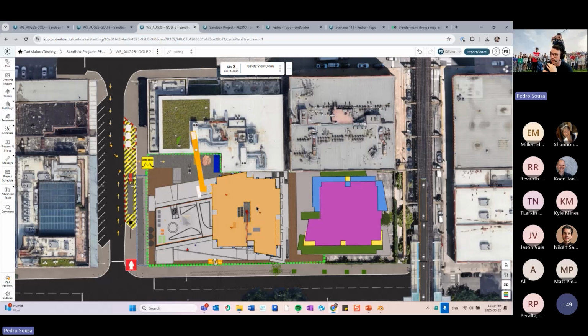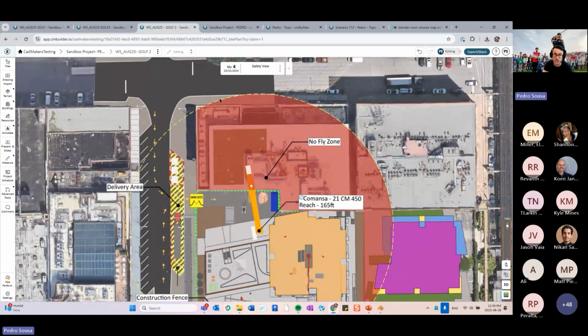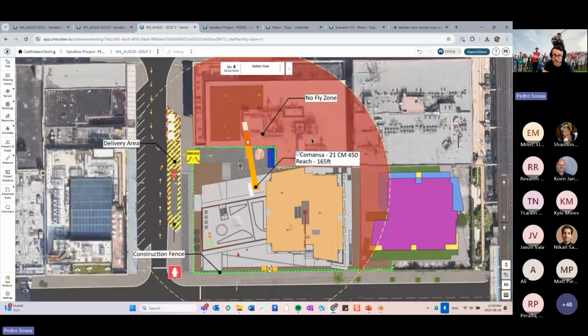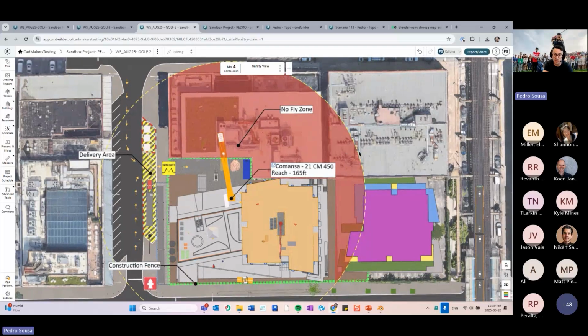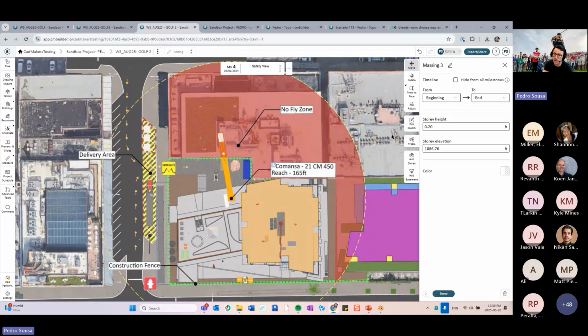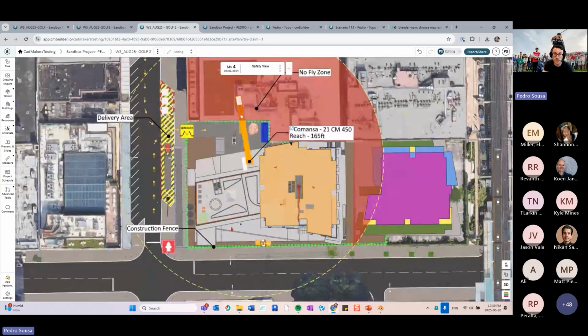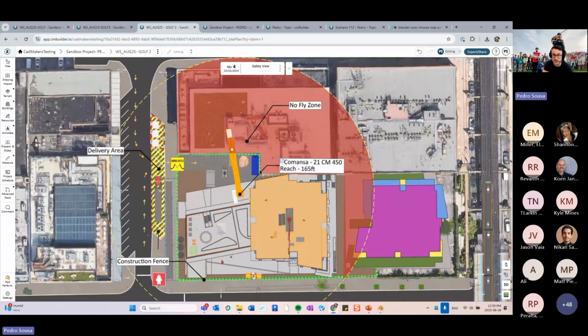Another point that I really stress is to really use the annotations. So callouts, lines, and zones, like I did over here, right? So I created a line to represent the crane radius. I put a lot of callouts to highlight elements in this view. I created a zone over here for the no-fly zone and so on and so forth. But also, one interesting thing is that you might want to refer to other documents, right?